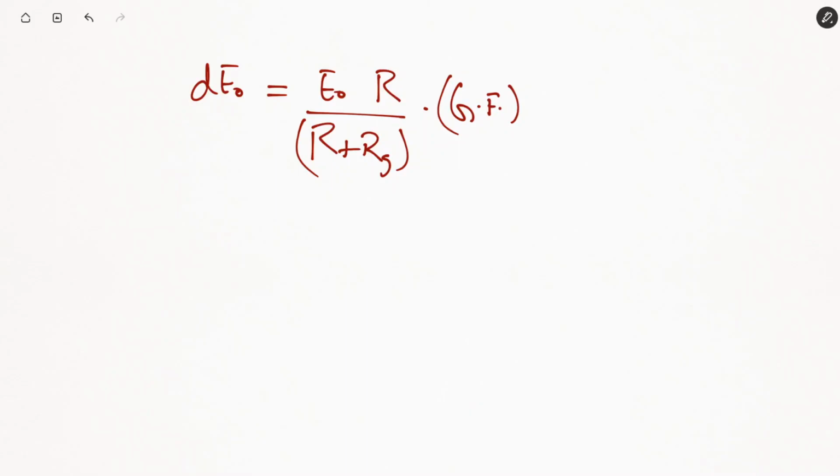So the value of R here related to Rg will be large, so that it will act as a ballast resistance, in order to keep the current in the circuit constant. So irrespective of whatever the resistance of the strain gauge changing, because of the external circuitry, the current will remain constant. So the nominal value of R is approximately 2 to 4 times Rg.